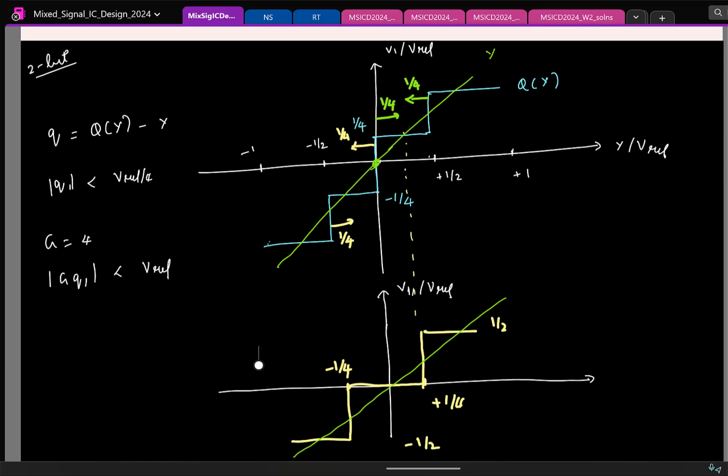again, see, what I was getting at is, the motivation to do this is the following. If I were to compare with 3 reference voltages, how many comparators would I need in a flash ADC? No, 3 reference voltages I need. No, 3 reference voltages are there. So you need 3 comparators. Fine. Now how many reference voltages do I have? 2. How many comparators do I need? 2. So it looks like the number of comparators has reduced. So that is one of the motivations.